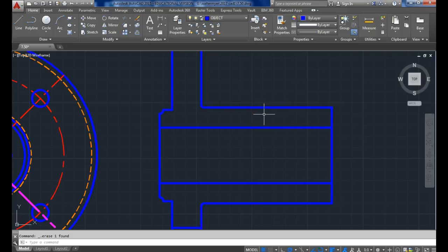On here, last thing before we do the hatching, there is a groove on the back here that's cut in. Alright, on the paper it tells me from this back edge to the center of this groove is 3 inches. So I'm going to do offset 3, bring this up. We're going to use offset again. It tells me the groove is 0.75 by 0.19 deep. So if I do the same thing, if I do 3/8 offset, offset, that'll give me these kind of boundaries for the groove.